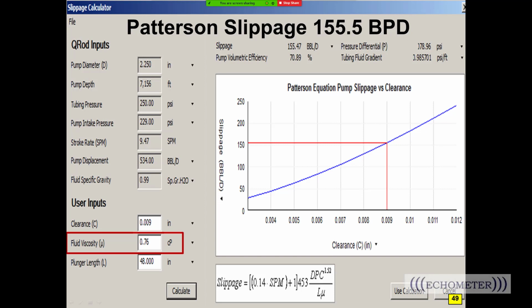That's what we talked about in the conclusion slides, that you can use this because it's based on a new pump. We've seen some wells in the field in Wyoming where the operator would use the slippage equation because they had a certain rate of wear based on the sand they produced. They knew that as they produced a well, over time they would get more slippage because the sand would start to wear the pump, and then they would increase the speed. So probably the number one thing that we don't know about is the pump wear. That would be my comment on that question.